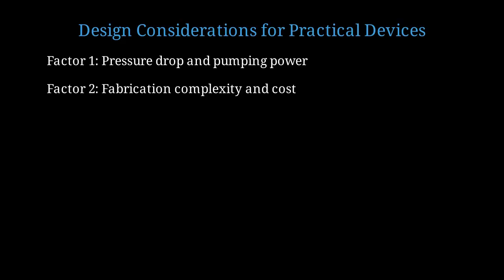When designing a real microfluidic mixer, engineers must consider several practical factors. More complex geometries create higher pressure drops. Serpentine channels with sharp turns and herringbone grooves both increase flow resistance. This requires more pumping power. Herringbone structures require multi-step lithography and etching. This increases fabrication cost and limits materials. Serpentine channels are easier to make.